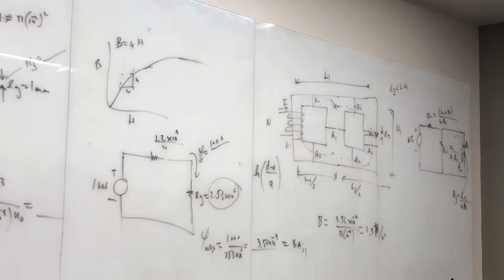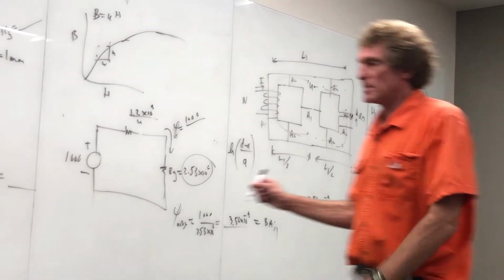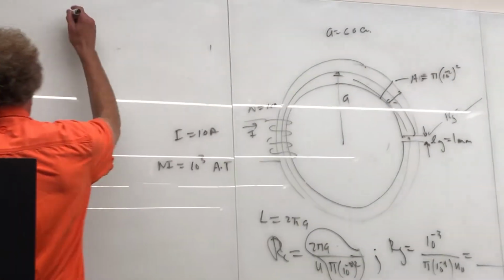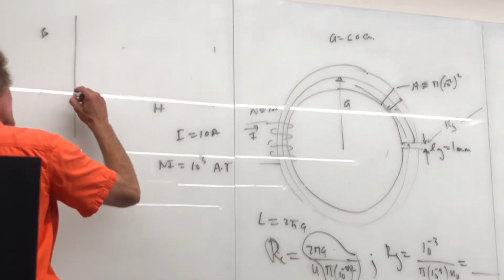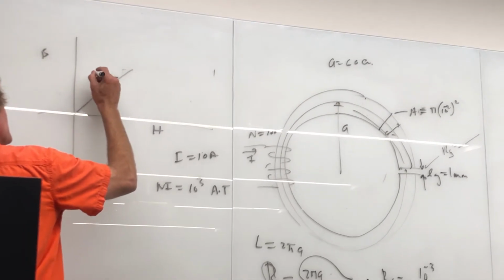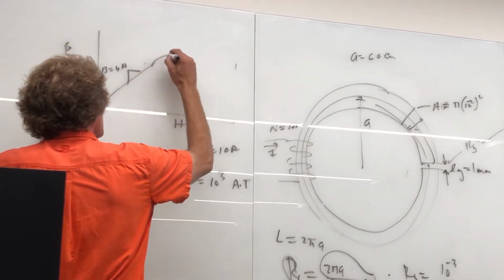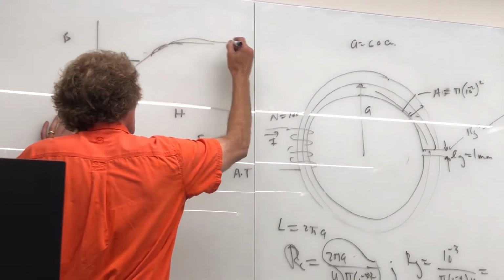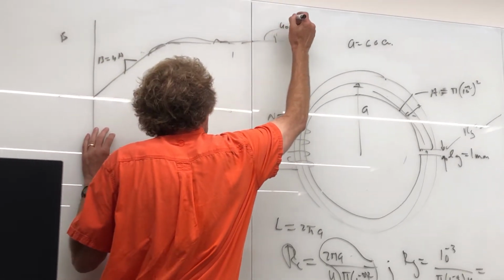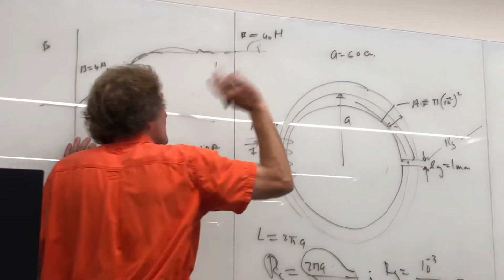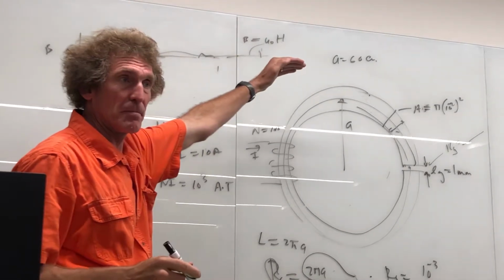That's the maximum, right? Now, he didn't show this well, but this is something to know about magnetic materials. In general, if you look at H versus B for all magnetic materials, it comes up, and this is just plain B equals mu H. But as soon as it hits this nonlinear hump and comes down, there might be some undulation. Out here, the slope goes to just mu naught times H is B. Mu relative becomes 1. It goes to mu naught, way out on this end.